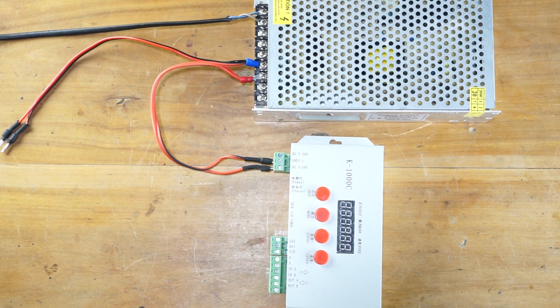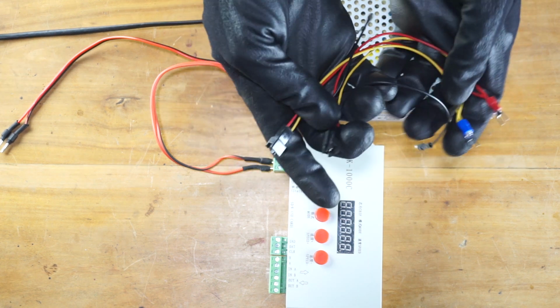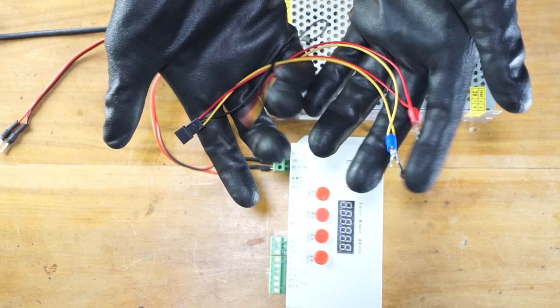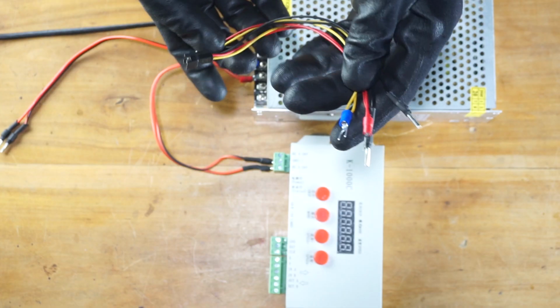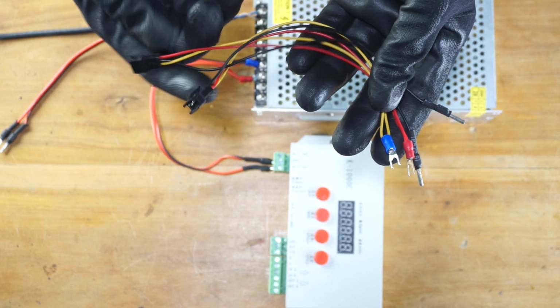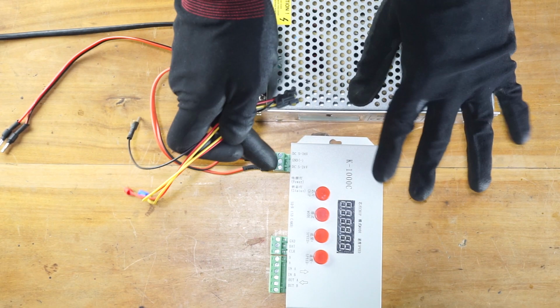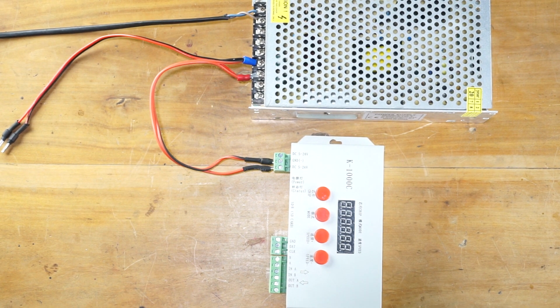To connect the pixel LED strings, I'm using these JST or SM3P connectors. You can buy it online. I have already put wire lugs at the wire ends. If you are using separate power supplies, you need to connect the grounds of these power supplies together to create a common ground.